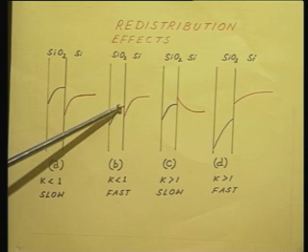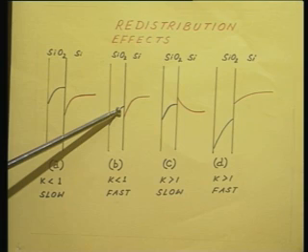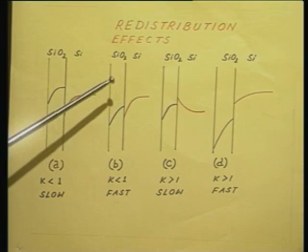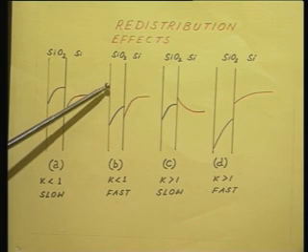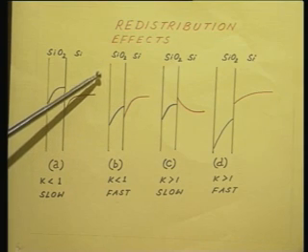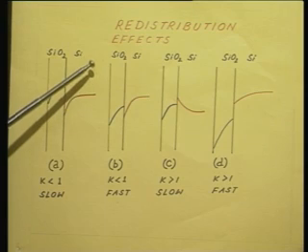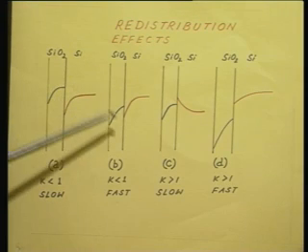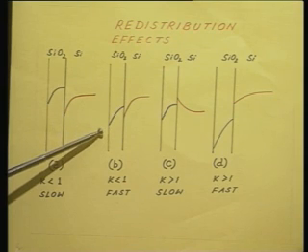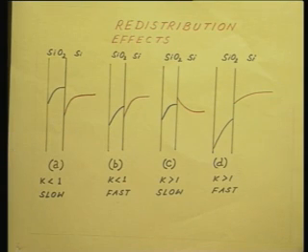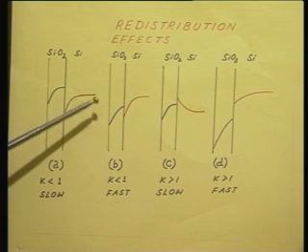Do you see? This is because segregation coefficient K is less than 1. But because of the presence of hydrogen, now boron can diffuse fast through the oxide. That is why you see the concentration is falling very fast, it is diffusing out through the oxide. That is the difference between these two pictures.